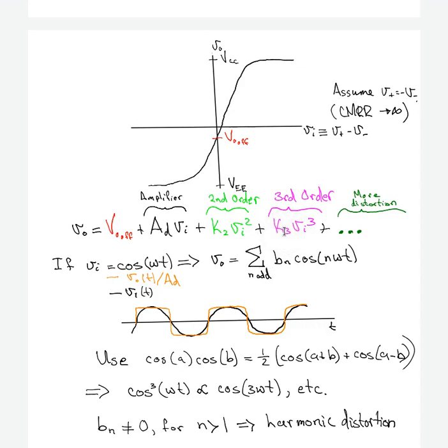Now, it's not exact, because if you use this on cosine of 5 omega t instead of cosine of 3 omega t, or if you do it on cosine 7 or 9 or all those other terms, you'll find that they also could have a cosine cubed omega t in the output, which would have a cosine 3 omega t in the output. And so this K3 really does correspond, or is proportional, to B3 in the case where the K4, 5, 6, 7, 8, 9, 10 and all those are very close to 0 compared to the K3 term.